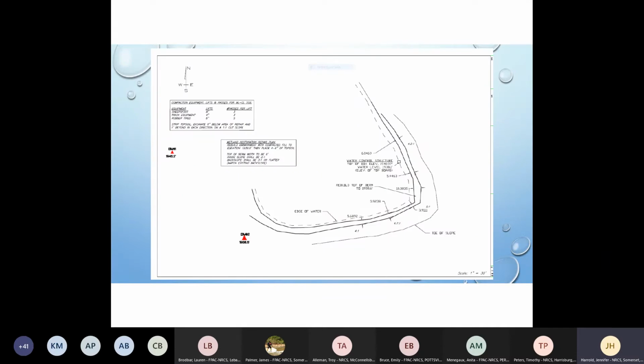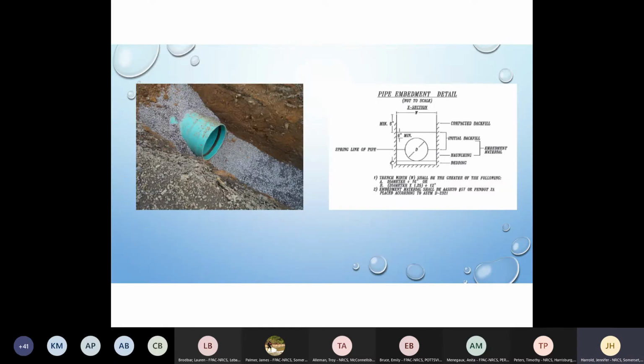This is an example where it was an embankment that was being repaired for muskrat damage from an easement. So they had a couple options. You have a sheep's foot roller, the lift, 8-inch lift, how many passes. So it's good to give contractors options of what type of equipment, the lift thickness, and how many passes, because they have options, and you're probably going to ask if it's not on there. So it's better to have it in the design ahead of time.